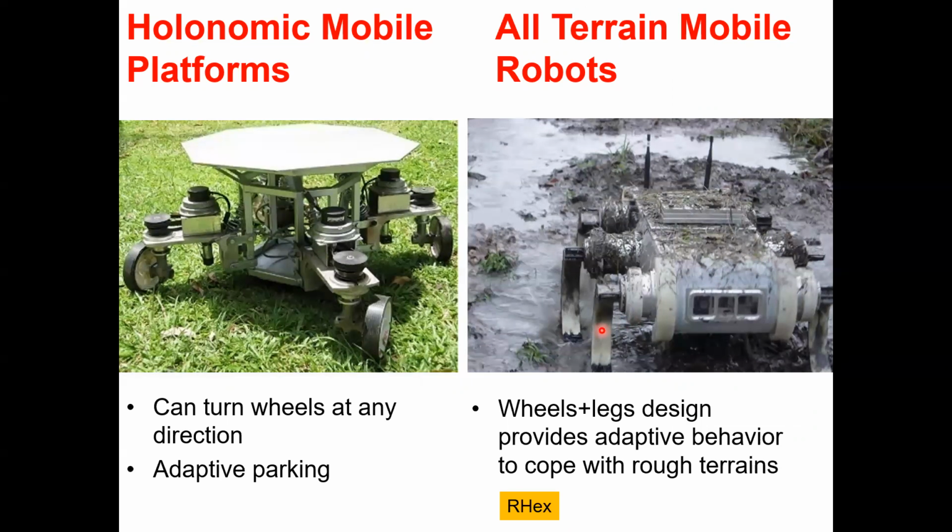If you look at these two platforms, legs and wheels, if you look at just legs, for example, legged locomotion is good for unstructured environments. Wheels cannot actually handle unstructured environments because wheels can get into a ditch and get stuck there, and there's no way to get out of that. You have seen many vehicles in mud and ditches and pits. It's difficult to get out of that. Whereas legs you can take very easily out of these situations because it's not a rotating thing, right? You can lift the leg and step by step you can move forward.